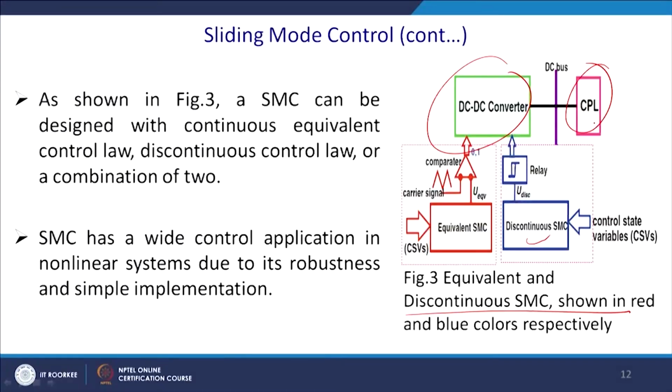So, what we can say here is that, as shown in figure 3, the SMC can be designed with a continuous equivalent control law as well as a discontinuous control law, or a combination of the two. Here we assume a continuous conduction mode, and the CPL may be in a discontinuous conduction mode. This sliding mode controller has wide control applications in nonlinear systems due to its robustness.